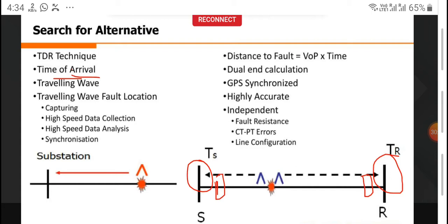But when these are of a length of 1 meter or something, when you're talking about jumpers, or let's say 100 centimeters, or whatever the length may be, depending upon the dimension of the line, or depending upon how you have placed your suspending insulators. Now, when you're dealing with a line that's traveling 400 kilometers, 500 kilometers, then this 100 centimeters or 200 centimeters gets multiplied by the number of transmission lines you have to take into account. Then this total net value comes out to be 1 kilometer, 2 kilometers, even as far as 5 kilometers. So you always need to calibrate the exact length of the line.